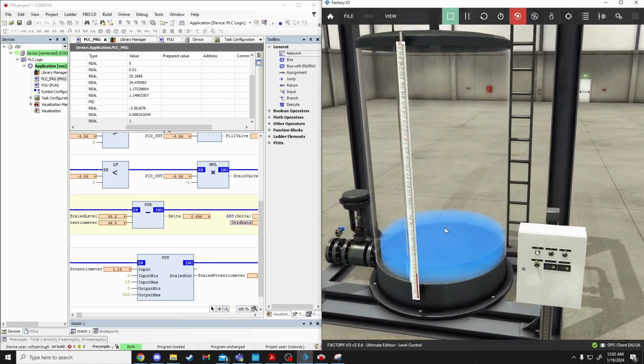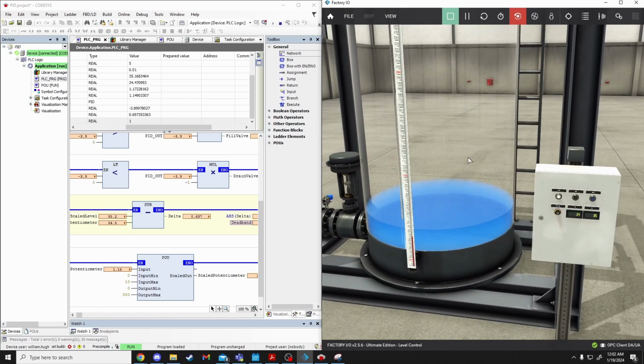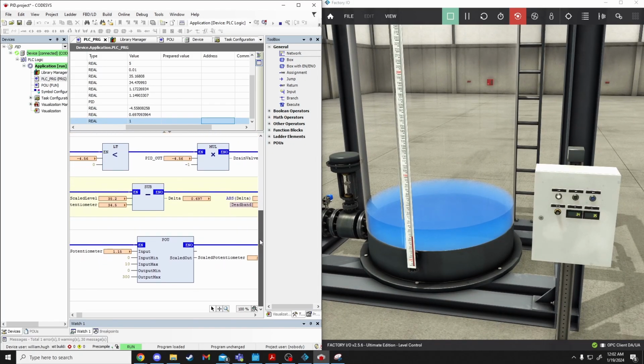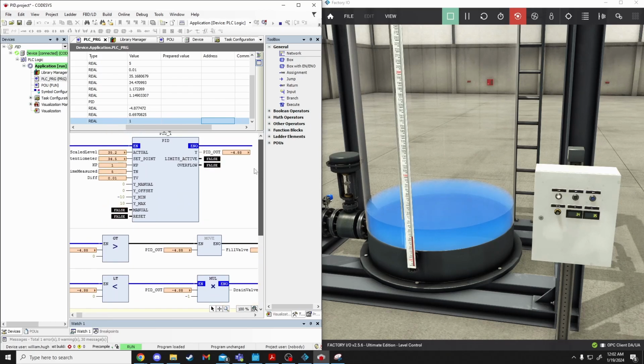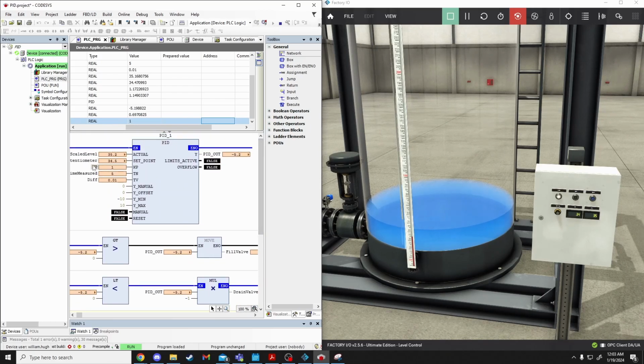It was the challenge. The PID has a lot of setup to it. You have to scale your values. It involves a lot of variables. But once you get it plugged in, it's as simple as figuring out a good gain value, and then you start tuning your integral and your derivative. There are guides for tuning PIDs. I highly suggest you check them out.